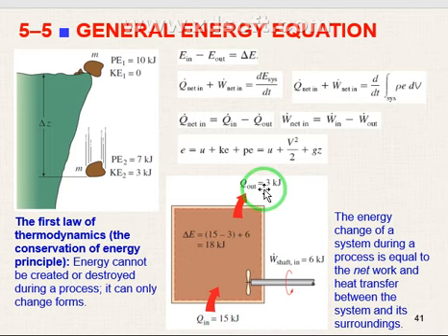I have a Q out of 3 kilojoule, but also I have another shaft energy in, rotational movement, of 16 kilojoule. So the delta E over this system, we have 15 in here, we have minus 13, and we have plus 16. So the delta E over this system is gonna be 18 kilojoule. You understand? So that's how we can understand the situation.